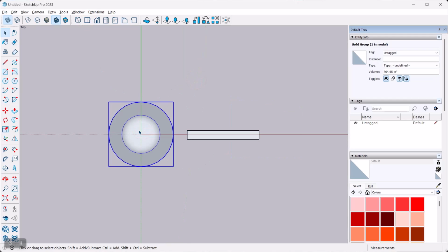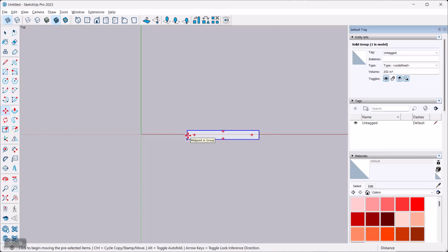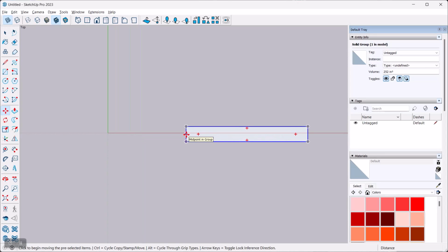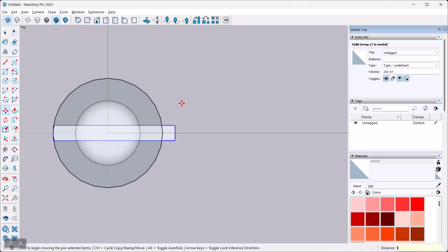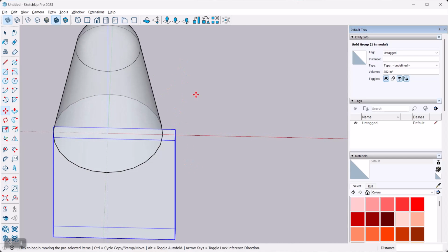Another useful tool for something like this is the hide tool. So what I do is I actually put hide on a keyboard shortcut so that I can quickly hide things. So that's what happened here. I didn't delete it. And then always use your snaps to get things positioned properly. Now I've got it nicely centered right there. I don't have to go too precise, because ultimately now we're going to overlap it.